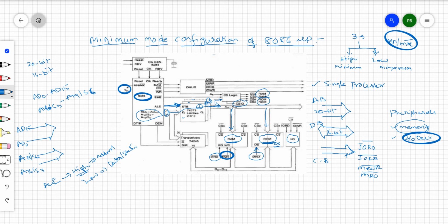The remaining lower address lines select one register among the selected RAM, ROM, or IO. Along with some higher order address lines, we have the BHE (bus high enable) bar and the A0 pin. The combination of BHE bar and A0 is going to be decided.